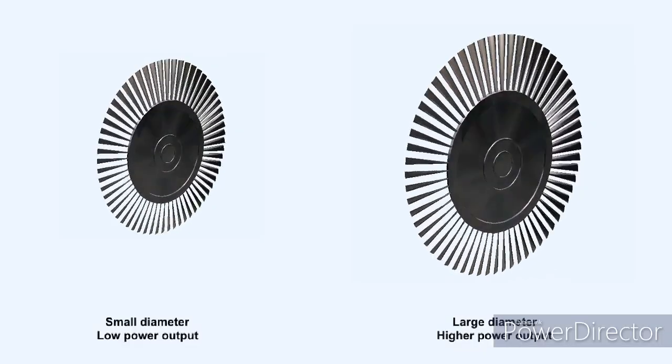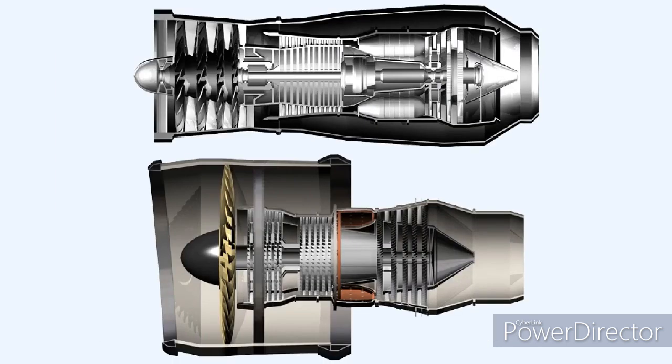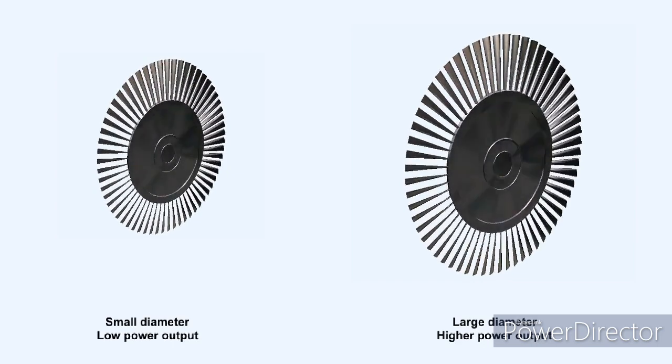The power output of a turbine can be increased by increasing its diameter. But this would have two detrimental effects. Firstly, it would increase the drag factor by requiring that the engine be designed to have a large diameter. And secondly, greater stresses would be imposed because of the greater centrifugal forces created.